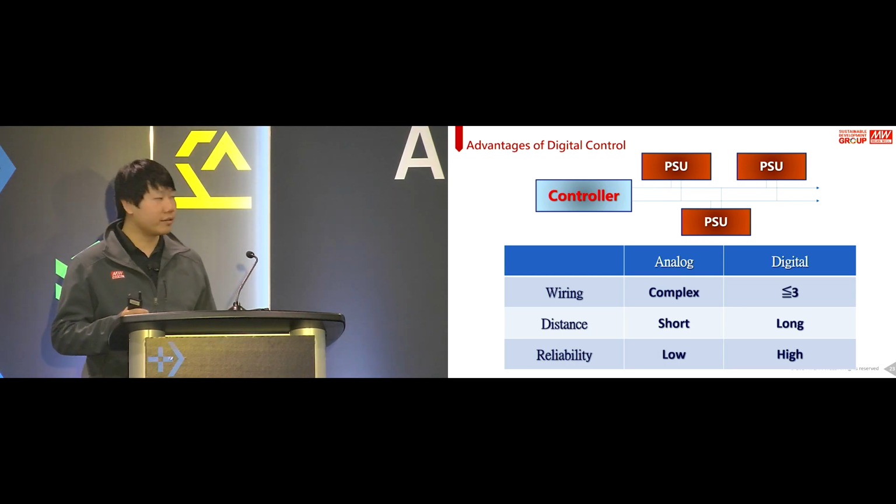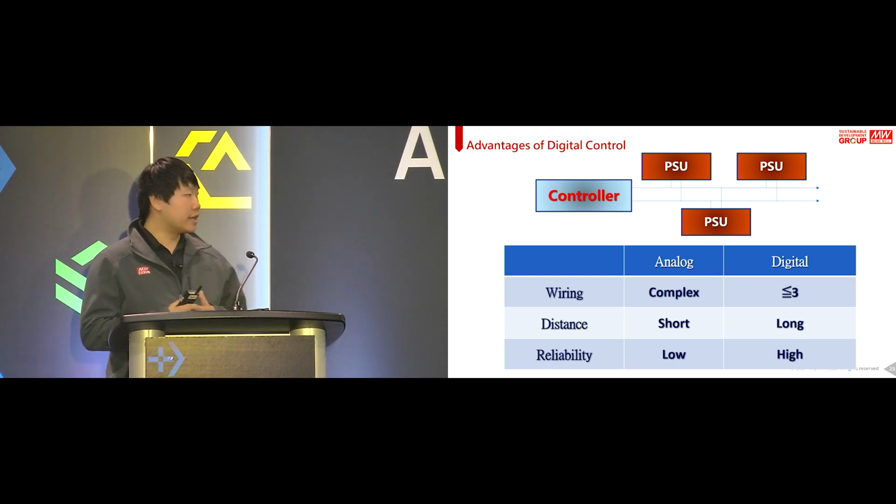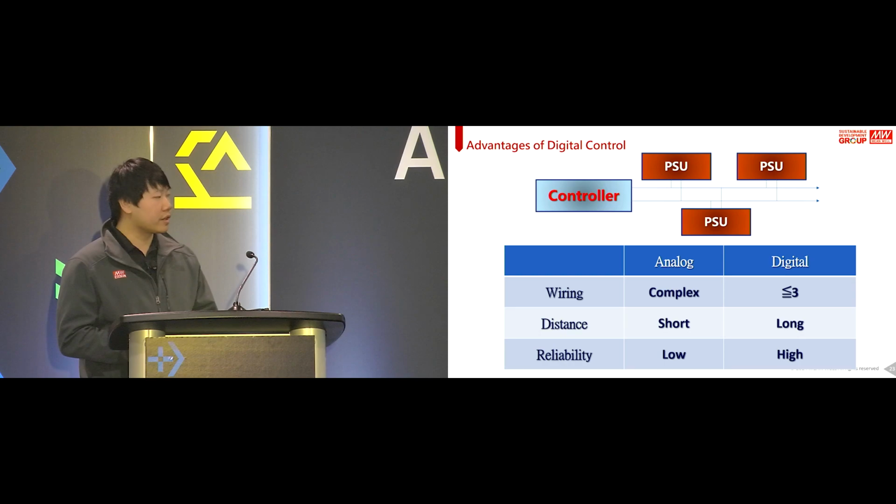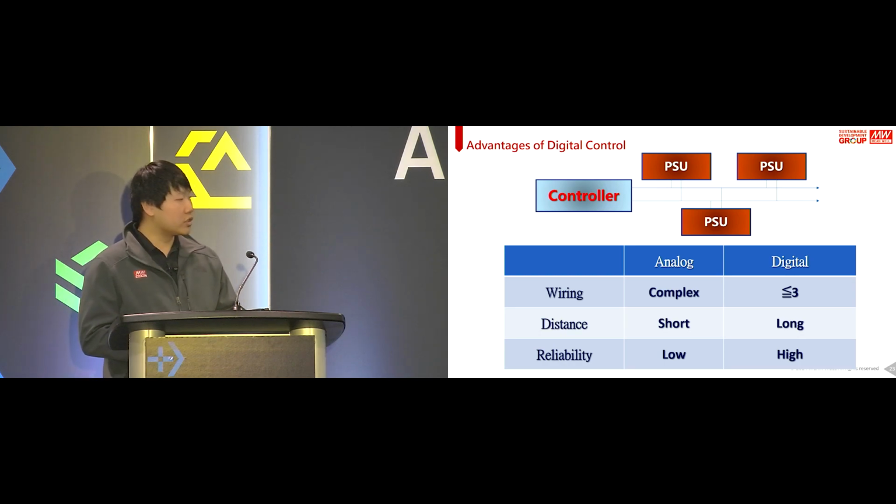For digital control, however, most of the digital protocols support a single bus for the wiring, and then you can wire multiple devices to the same controller. So the wiring is very much simplified, and the distance for the communication controls can also be long. And if you're utilizing modems or products that support remote monitoring features, you can be miles or hundreds of miles away and still monitor the status of the power supplies and your system. Which in turn supports higher reliability system designs because it has more robust and more flexible monitoring features for the power supplies.